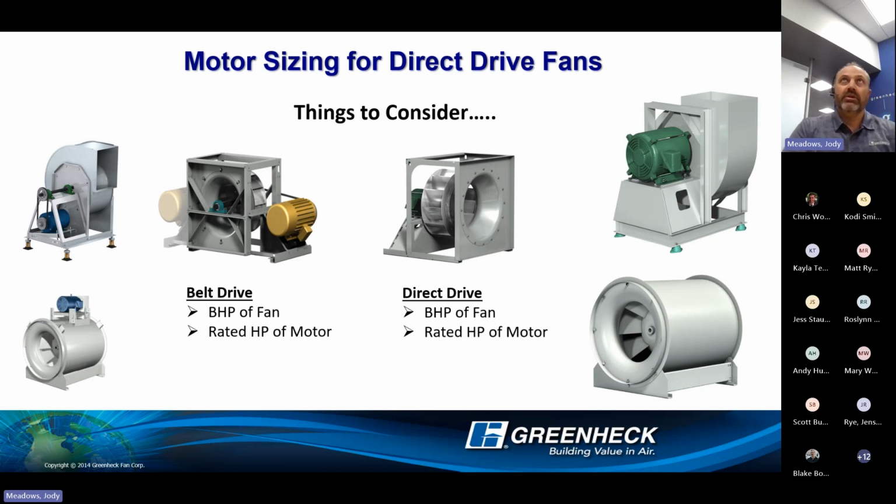The next topic is sizing motors for direct drive fans. All right, so when we think about sizing motors for a belt drive fan, there's a couple things we think about. So, brake horsepower of the fan. We know what the brake horsepower of the fan is for a specific design point. And then what we're thinking about is what's the nominal horsepower of the motor that I'm going to apply. So if you have a 4.5 brake horsepower fan, a 5 horsepower motor is probably enough.